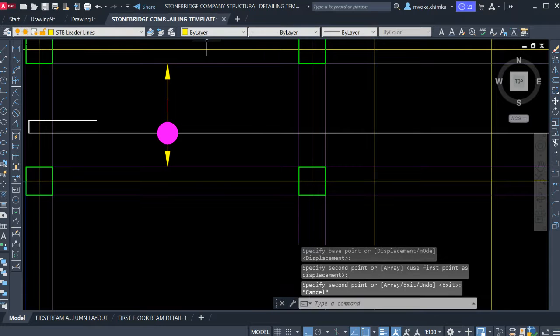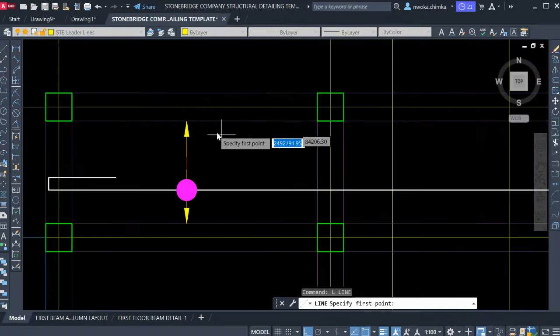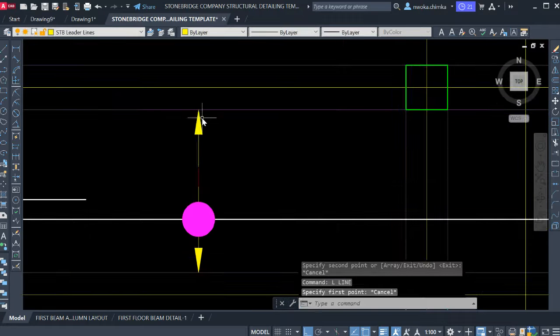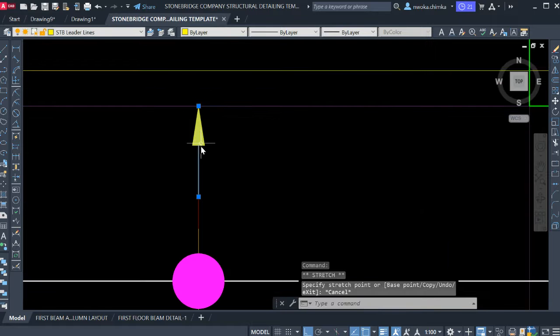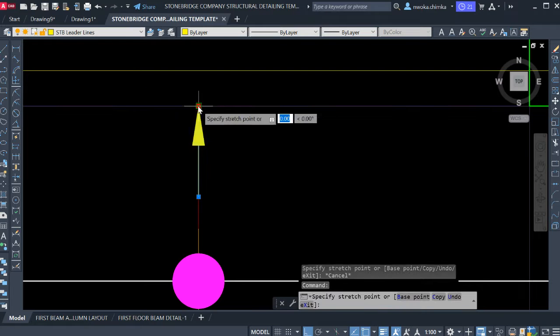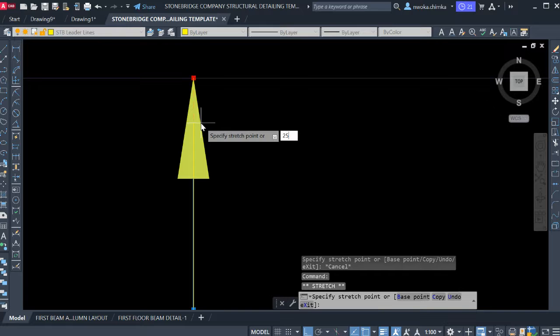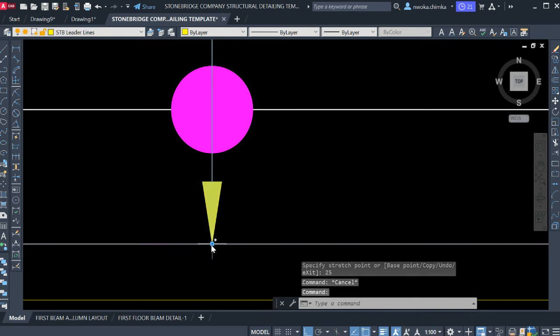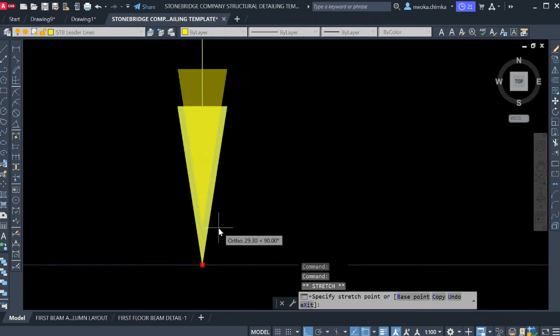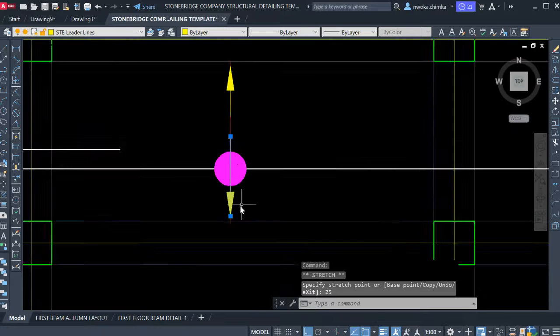Now the next thing is to place a call out line for, okay, no, I have not yet put my concrete cover for this, so I'll click on this and go down by using 25. The same thing happens here, because you must take into consideration the cover of concrete 25 also, and then press this.